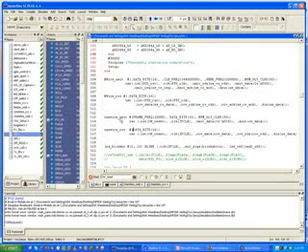So let's go back to the simulation file. I've instantiated the transmitter, and right now it's going to transmit just a value of 035C, just for fun, for 16 bits. I take the data out of the transmitter, call it OW data, and run that right back into the receiver, the data in pin.